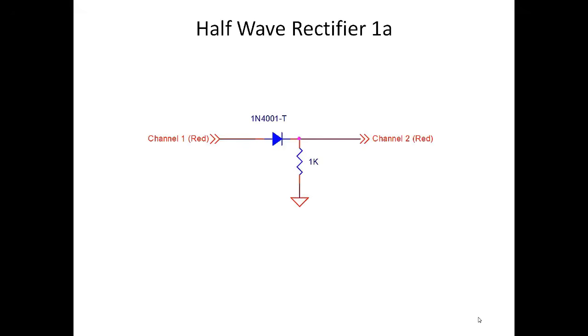The first measurements that you need to take are the peak voltages for the half-wave rectifiers. What we're trying to find is the voltage drop across these different diodes. Remember that the diodes don't start conducting until you have exceeded the forward voltage for the device. To measure this, look at the difference in the peak voltages of the input and output waveforms.